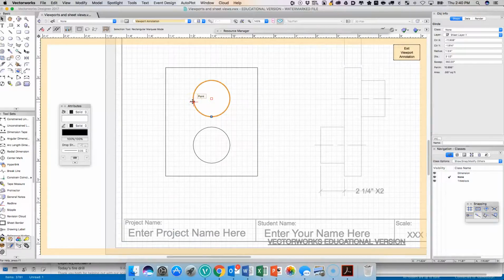So what we're going to do, and this is where we fool Vectorworks, is change the fill to none, and change the line to none. Now there's a line there, you can see the circle, but there's also our phantom circle. So I'm going to do the same thing over here. I'm going to draw this circle. Now this guy I can leave if I want, but I'm in the habit, anytime I have, quote unquote, phantom circles, I pull the color out of them.